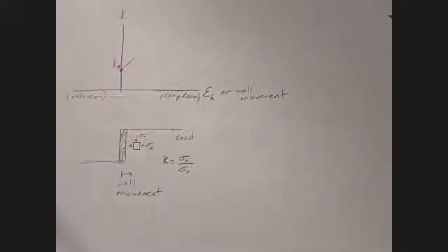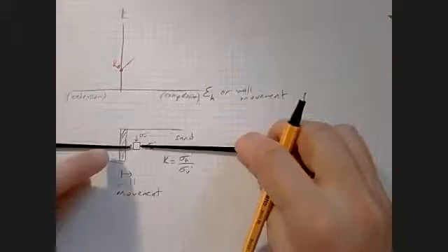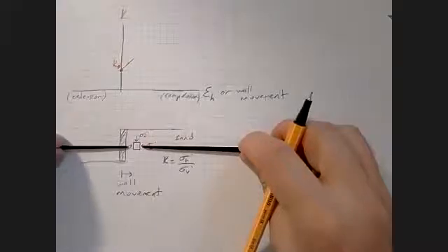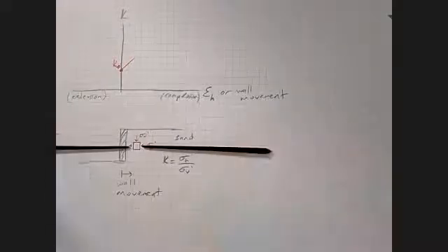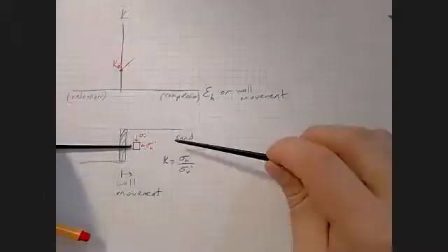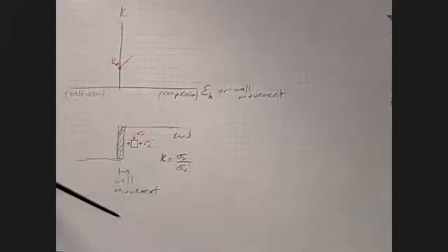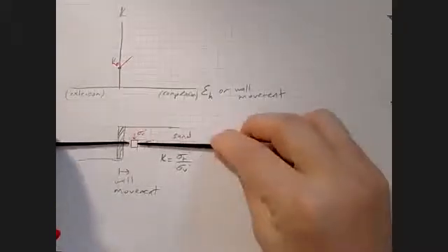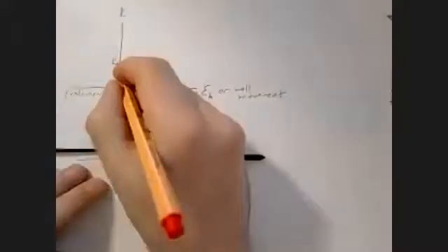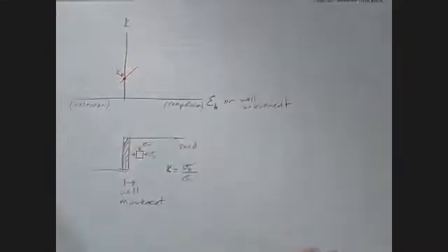And similarly, if I move the wall away from the soil, I'm going to be relieving the soil of stress. I can't really apply tension to it because soils don't take tension. It doesn't work like that. But as you move the wall away from the soil, the sand will move, it will flow, and it will be able to still apply some stress. But you are relieving stress, so it goes down from there in the extension direction as well.